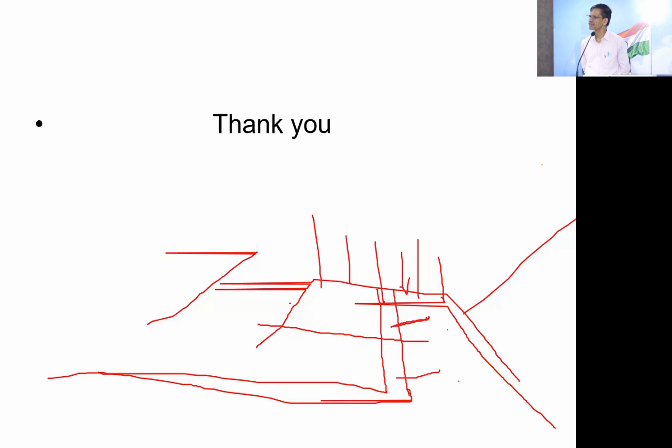And you don't have any issue in putting the liner there? We are providing liner on the base and the dike slope. When you install the liner along the upstream slope of 2.5 to 1, you don't have any issue. The contractor can easily put that.